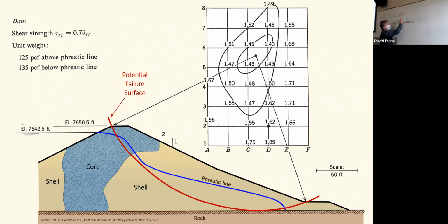And then normally the water table would do something like this. But if you put this blanket here, that becomes the discharge point. That's so infinitely permeable compared to the rest of the dam's shell that the water table actually does this. So you've successfully lowered the water pressure near the tailwater, and that's a good thing, right? The farther back you construct this, the steeper the hydraulic gradient, but again, you're dewatering the back end of it.